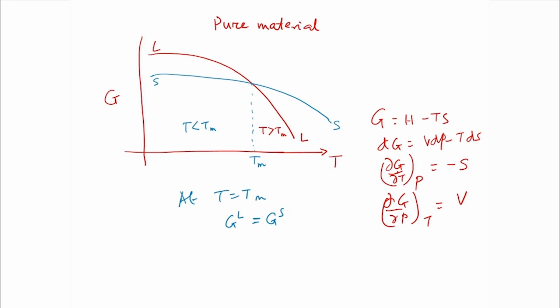Am I clear? So therefore, in a bulk material, this is what happens. Because in the bulk material, free energy is given by this. We don't consider any surface energy effects, because surfaces are neglected. But as you know, for a nanocrystalline material, G total, I already told you, is G bulk plus G surface, right? This must be the case. You can no longer ignore it.